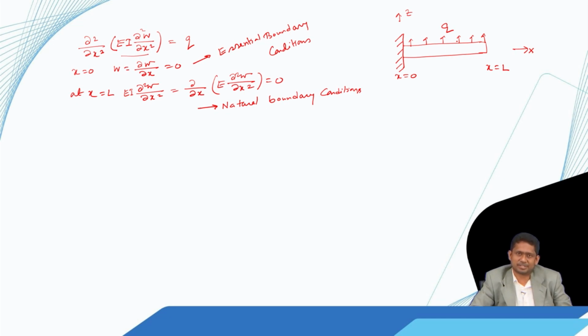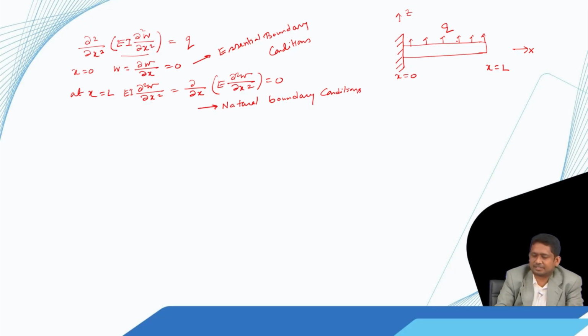In case of laminated composites, even with a regular geometry, it sometimes may be difficult to get a closed form solution. Depending on the sequence in which the plies are put, or depending on the boundary condition, there can be cases where we cannot have analytical or closed form solutions. At that time an energy or virtual work based method helps us. So we will understand this method with the example of this structure.